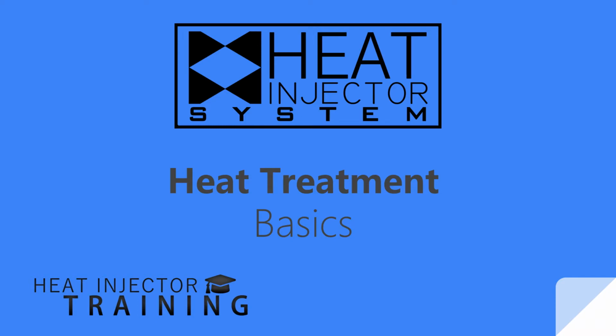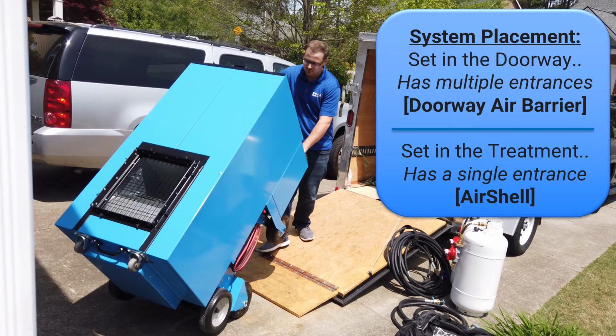Let's get into it. When you're performing a heat treatment with your heat injector system, one of the first decisions that needs to be made when you show up to a job is where to place the heat injector. It could either be placed in the doorway to the home, which would be using a system called the doorway air barrier. Like it says, it creates a barrier in the doorway and allows the heat injector to have access to fresh air for combustion, for cooling the controls, and cooling the motor. This is also used to pressurize near the end of the treatment.